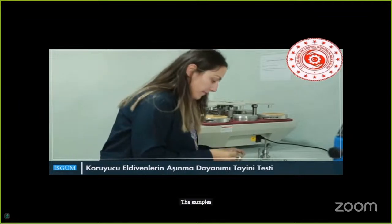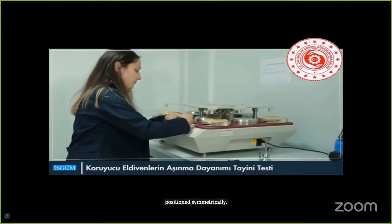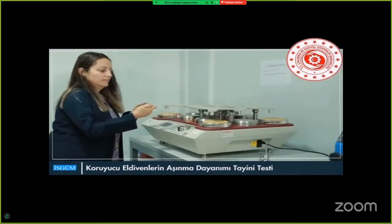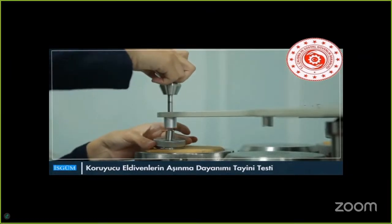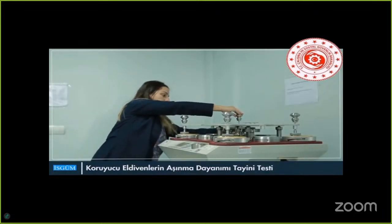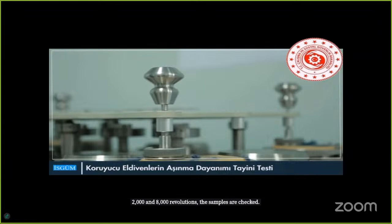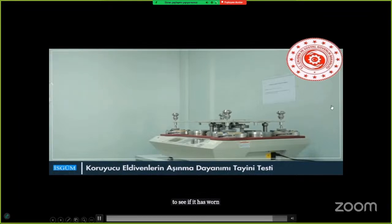The samples go onto the carrier. 9 kilograms of pressure will be applied to the samples, positioned symmetrically. The device is set up and the test starts. At 500, 2000 and 8000 revolutions, the samples are checked. Wear on the sample is visually inspected to see if it has worn at least 2 millimeters from the corners.